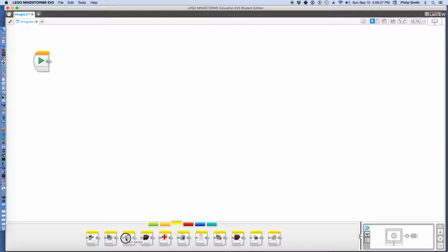The next sensor along is the gyro sensor. It also has a port. You can choose 1, 2, 3, or 4, or wired. The modes are measure angle, where the data wire gives you angle. Measure rate. So measure angle is what angle the gyro sensor is pointing in along the axis of rotation that the arrows on the gyro are in. So if you have a robot that turns and your gyro doesn't change, that's because your gyro is either not plugged in, on the wrong port, or it's rotated sideways on your robot. So it's actually measuring whether your robot tilts up or not.